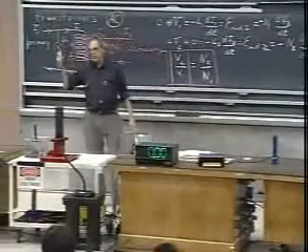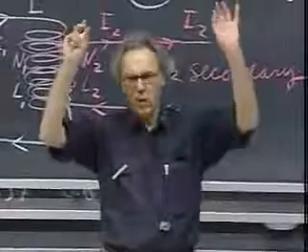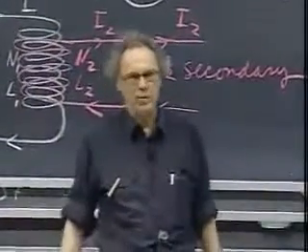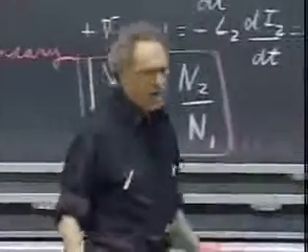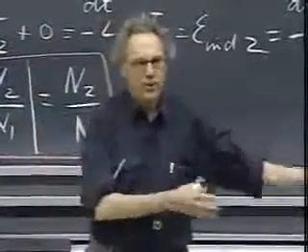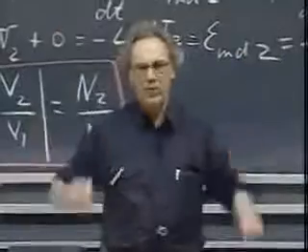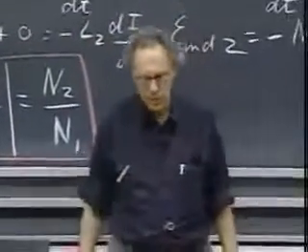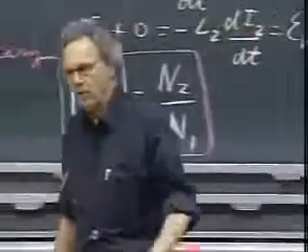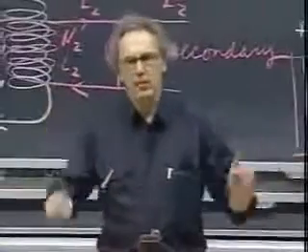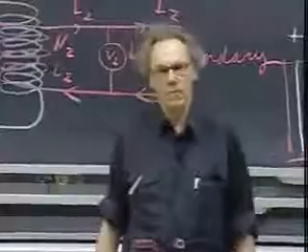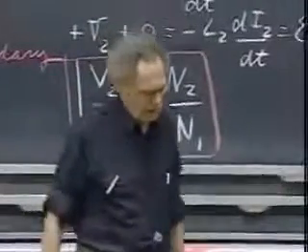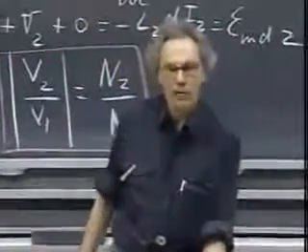The power station puts the electricity, so to speak, on the line at 300,000 volts. We discussed that earlier, why they do that at such high voltage. So they have a transformer from their generator to transform the potential up to a very high value, to 300,000 volts. When it arrives at Boston, it is stepped down to 12 kilovolts. And so there are transformers, which you see, huge transformers, which have a ratio N1 over N2 of 25.